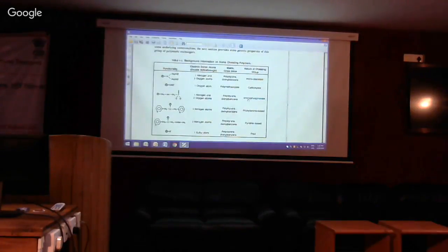Now, keep in mind that the higher the number of sites where it can bind, the more selective the resin will be. That is correct. But we also have to think of the reverse. When you bind the heavy metal to the functional group, after that you have to get it out as well, regenerate it as well. So there is always a trade-off.